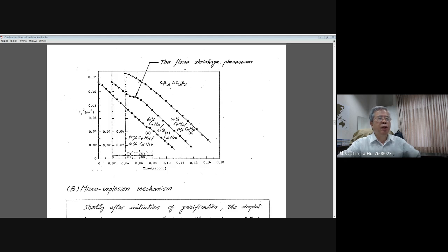And these behaviors are enhanced by increasing the percentage of C16. Moving to the initial period, I mentioned that when you add 80% C16, you will find in the earlier period the line becomes more curved and does not show a linear decreasing line. This tells you that in this short period, you can evaporate the 20% C7 very fast from the surface of your liquid. But the rest, the 80% C16, at that moment starts to absorb heat for preheating.